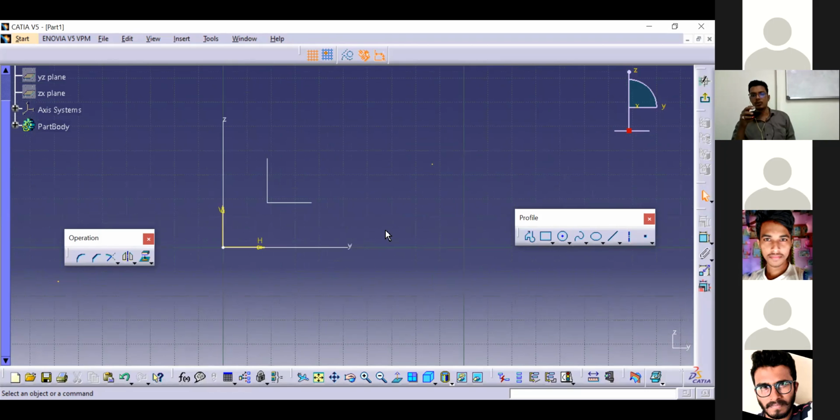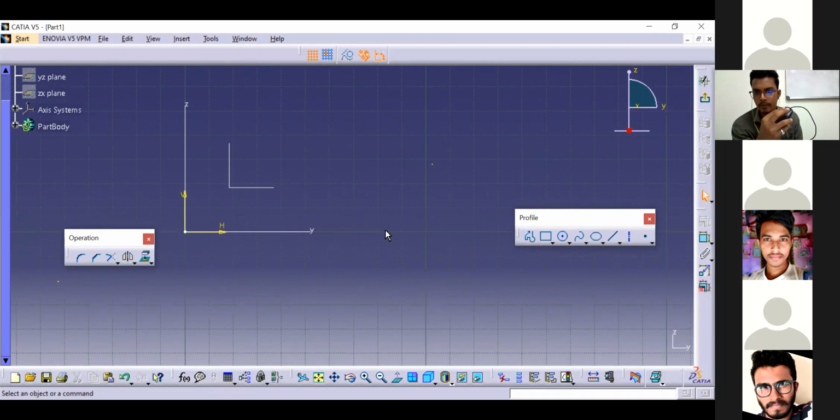If you want to zoom in and zoom out, it's kind of tricky. You just need to click and hold this cursor button. Once I click it, you can notice the cursor on the screen changes to a plus mark, right? Yes, sir. Now what you have to do is give one right click, without releasing the other button, just hold it as before. Give a right click once and leave it. Now you can notice the cursor has changed to a double arrow mark instead of the plus mark.